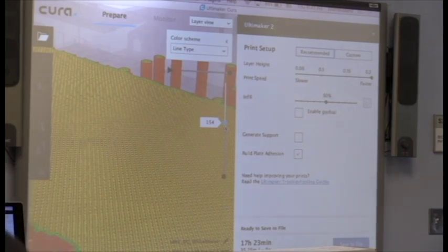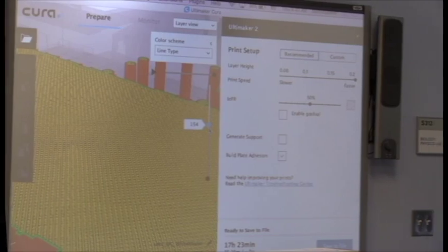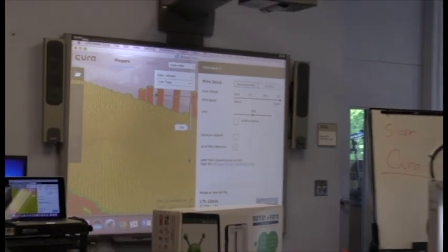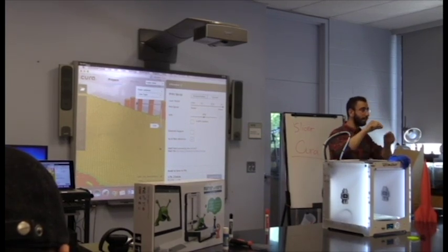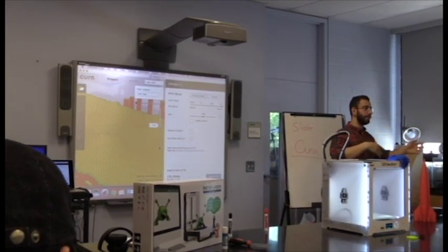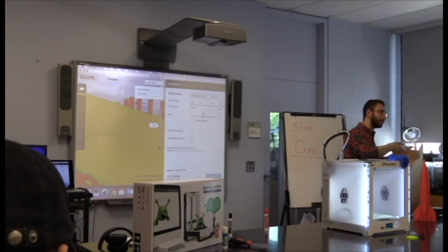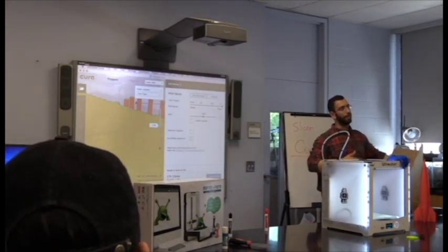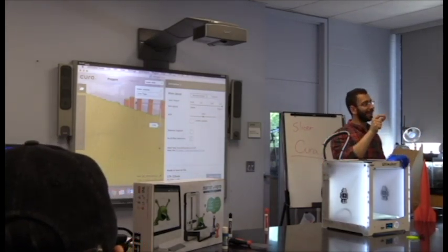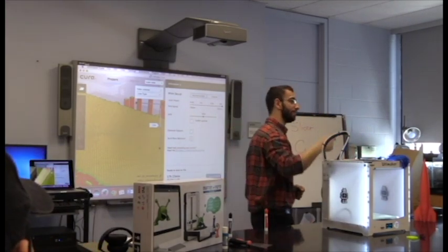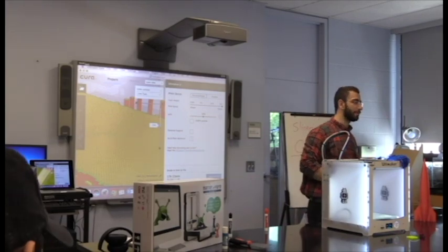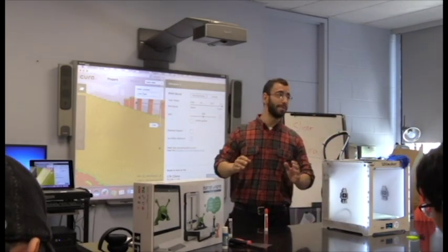One would use 100%. Let's say I'm making a phone case, okay? In a phone case, I have very thin wall items. Thin walls, if you tell it 10%, it's going to try to do that 10%. It'll do a little line every centimeter and then exit on the other end, and that's going to give you a flawed file. You're going to have gaps, it won't be structurally strong. Whenever you're dealing with thin walled stuff, you want it to be 100% infill. So if you're printing a phone case, you want that to be 100% infill.